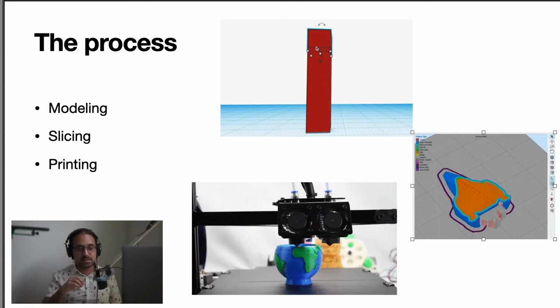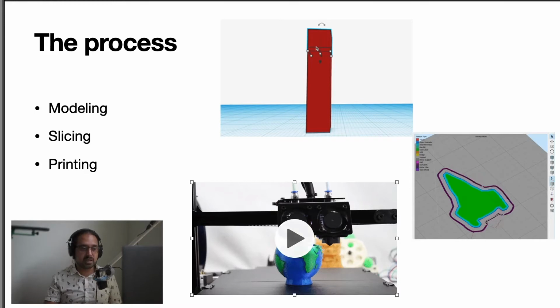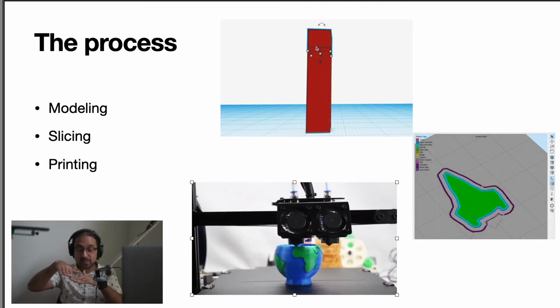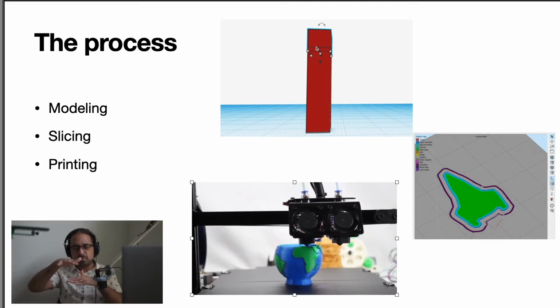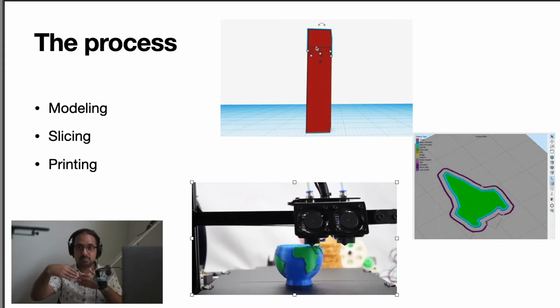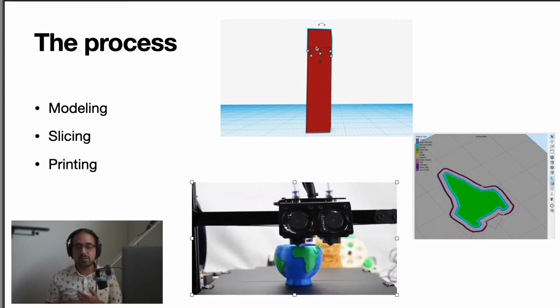And then those slices, or the slicing, is turned into a series of control instructions for the printer. So it will basically tell the print head how to move relative to the print base, and it will generate the model layer by layer by layer. So here's a fairly standard example, and at this point you would have been fairly familiar with this. It'll turn that slicing directly into what's called G-code instructions. For most printers, it's called G-code, at least anyway. And those G-code instructions will tell the printer what to physically do. And you can get pretty fancy with the G-code.